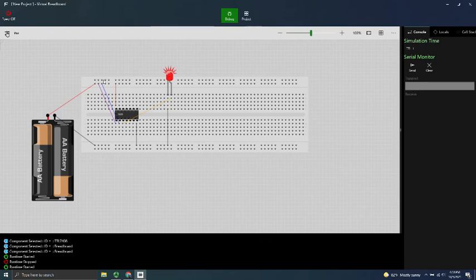And over here, the same thing. This whole row up here is ground. And the second row underneath it is power, because I've connected that there. I could have easily connected this to the very top, and that would have given me power up on top as well. And then the chip, if you haven't taken or you're not taking digital and you're just looking at this video to understand how to use a breadboard, that's perfectly fine.